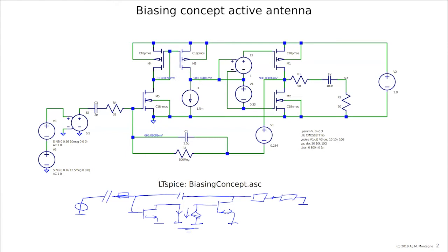But now we have to add, of course, the bias sources, and here is the bias source for the current mirror. So this one is simply shorted, and how it is biased I will discuss later. The first stage, how it is biased, I will discuss later, and then we have the current here. This part is the push-pull stage, biased with two voltage sources. One of them is controlled with a gain of one, to take this point exactly in the middle, but this is not really necessary here. But I just left it in how we designed the stage.